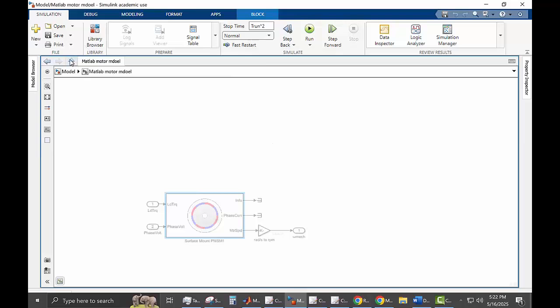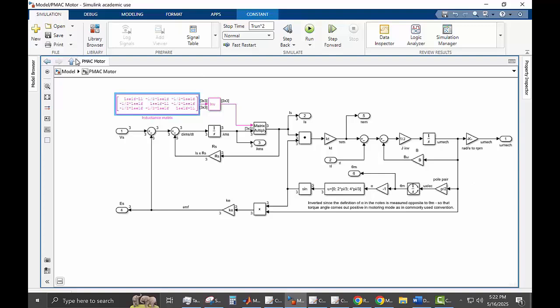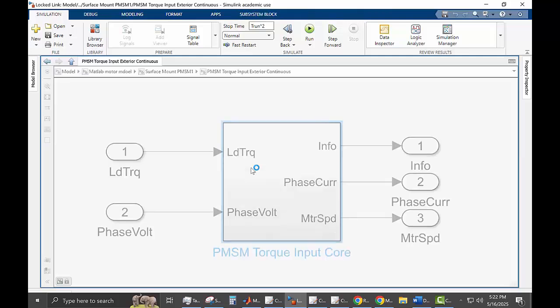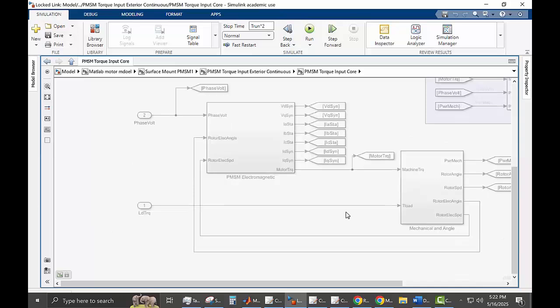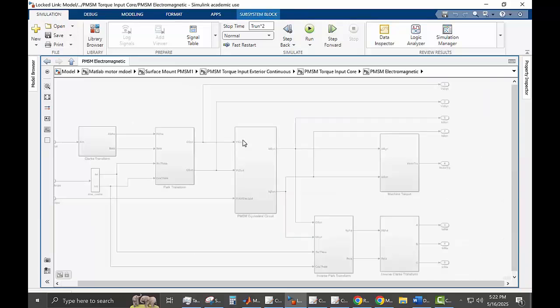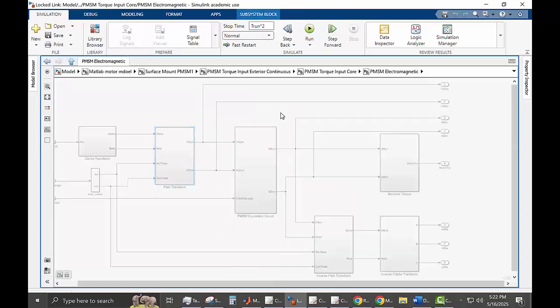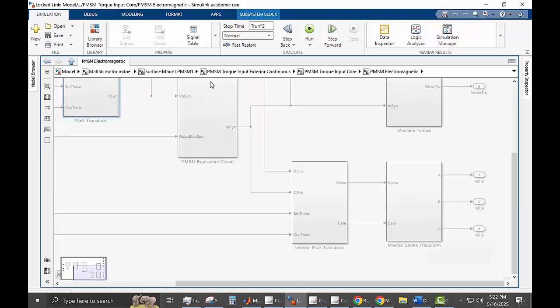And click OK and you run this model, you should get the same answer as you would get with the model that we have. If you scope a little bit and look under the mask, I don't know who designed this model. It's unfortunately unnecessarily complicated. Even if you use DQ transformation, the model comes out actually pretty easy. Just a bunch of equations which can be simplified, all of this expression that's here. So it's unnecessarily complicated. When we look at the DQ model, we will look at how to do this. But there is no need to do this model in DQ at all.